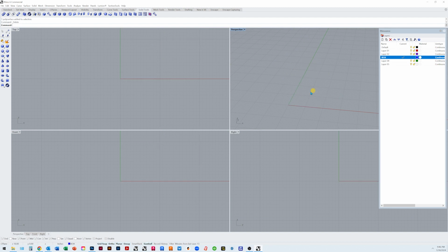So let's look at how we would do that if we wanted to do it from measured dimensions. Let's take that box, and I'm going to start here in the corner. If I want to build my box 10 on one side, 20 on the other side, I want to go up here to the top where it says other corner of base or length, and I want to do 3-point. That'll allow me to put in the length and the width of the base of the box. So I type in 10 and then I left click, and then I can type in 20.